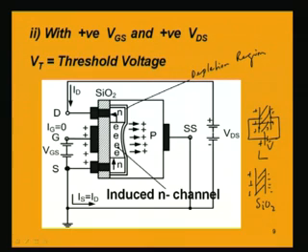So, this field will now be controlling the current flow through the MOSFET. The current flow from drain to source, which is because of the flow of electrons from the source to drain, will now be controlled by this field which is present in the parallel plate capacitor formed on the two sides of this insulating material. So, the name field effect transistor is significant, because that field is coming into existence, which is now controlling the current flow.